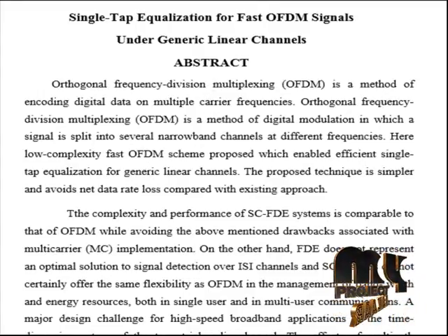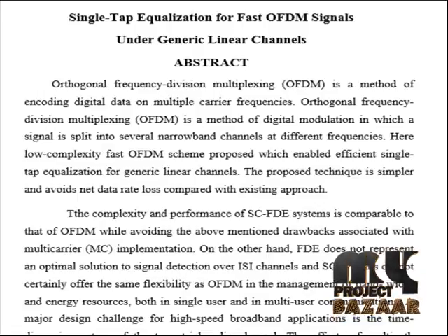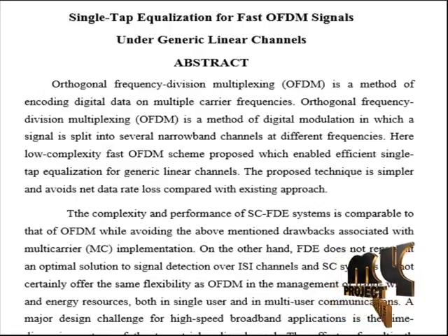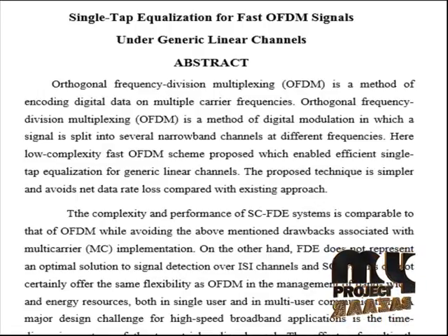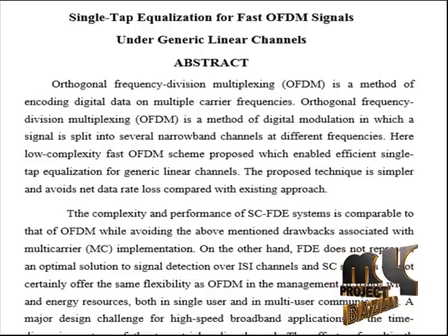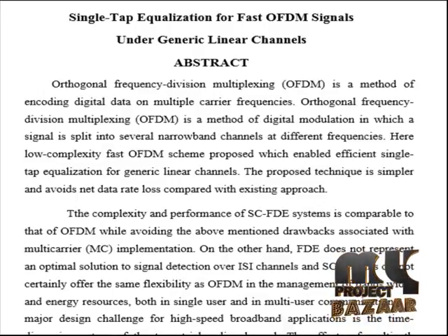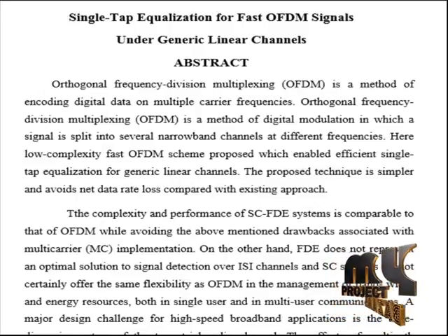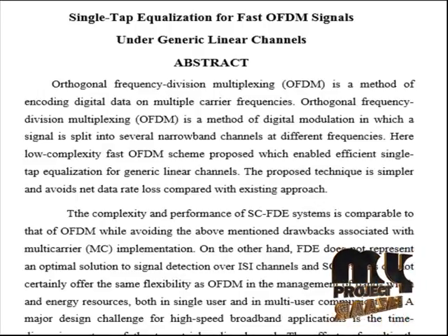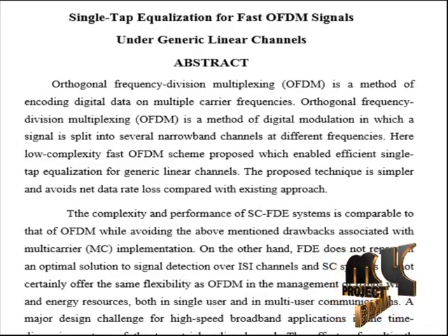Orthogonal frequency division multiplexing is a method of encoding digital data on multiple carrier frequencies. It is a method of digital modulation in which a signal is split into several narrowband channels at different frequencies. A low complexity fast OFDM scheme is proposed, which enables efficient single tap equalization for generic linear channels. The proposed technique is simpler and avoids net data rate loss compared with the existing approach.